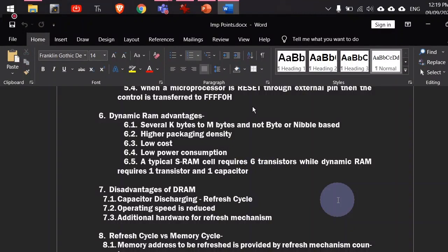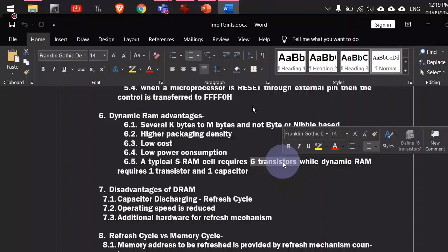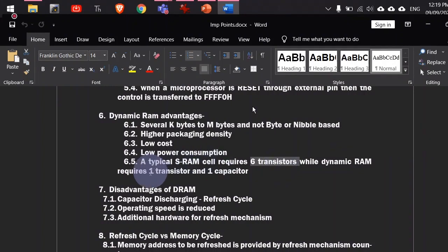Second one seems to be a better choice, but then there are certain problems. If you make a circuit using only transistors, the transfer of the data between those six transistors will not change the data itself. While if we use one transistor and one capacitor, it will be able to accomplish the work of six transistors, but the transfer of data between transistor and capacitor will lose the actual data originally.